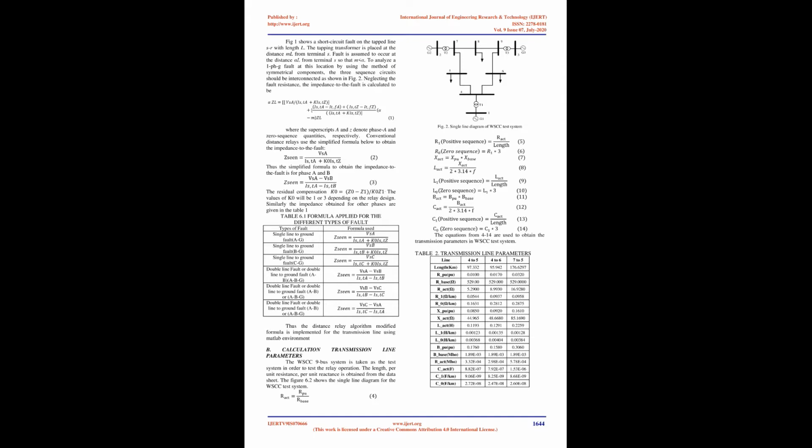Several operating coils can be used to provide bias to the relay, allowing the sensitivity of response in one circuit to be controlled by another. Various combinations of operate torque and restrained torque can be produced in the relay. A relay can respond to current in one direction differently from the other by using a permanent magnet. Direct current relays are known as polarized relays. Reverse current into a generator is an example of these polarized relays. The principle is extended with a polarizing winding connected to a reference voltage source for AC circuits.